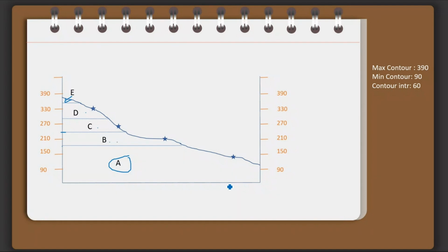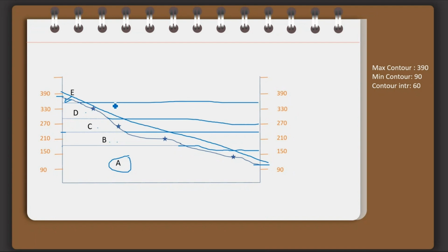So from this geological map, I can interpret that the area has 6 layers which are horizontally arranged, and the maximum height of the region goes around 380 meters and the minimum height goes around 100 meters, and it is a gently sloping region. And from the geological history, I can even interpret that all these rock layers must have been deposited as horizontal layers in this region, and due to weathering and erosion processes, this area has been cut away, and as a result these rock types have created a topography something like this.